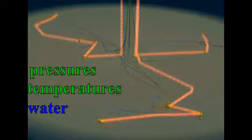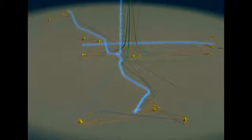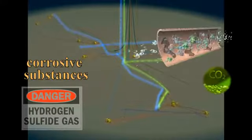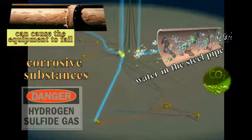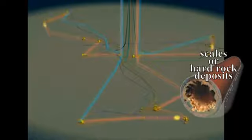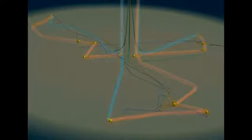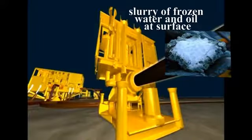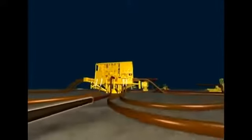Pressures, temperatures, and water levels in the reservoir must be monitored and controlled. Corrosive substances like H2S gas, CO2 gas, and water in the oil can destroy the steel pipe, eventually causing the equipment to fail. In addition, the production of scales, or hard rock deposits that build up on the inside of the pipes and valves, and hydrates, or a slurry of frozen water and oil at the surface, can also cause problems by restricting the flow of the hydrocarbons.